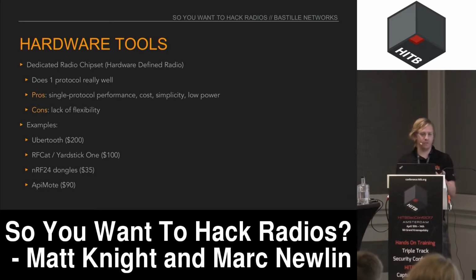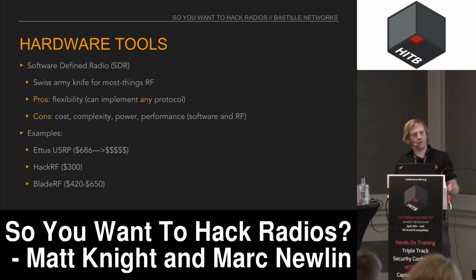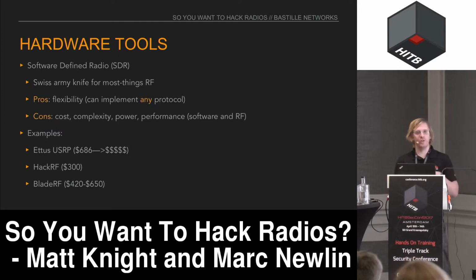Then on the software-defined radio side, the big difference between a SDR and HDR is that an SDR can be reconfigured on the fly. So you can tune it to different center frequencies, you can set different channel bandwidths, and instead of the logic that makes it a Wi-Fi radio or a Bluetooth radio living on the hardware, it sends the raw radio data to your host computer or an FPGA, and then the logic that makes it operate on a specific protocol lives in software.